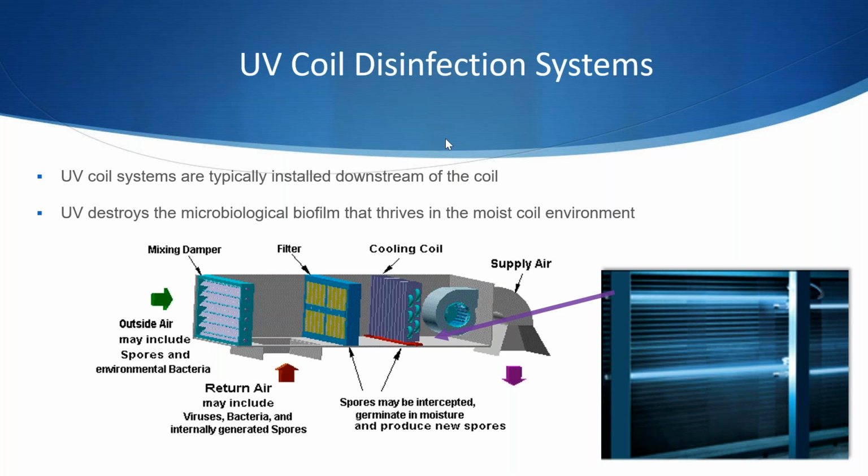So if their goal is only cleaning coils, then the best location is on the downstream side of the cooling coil, with sufficient space there to be able to space it far enough to have the irradiation cone from the lamp spread out and cover the fullest space of the coil possible. On the drain pan side, so you're able to irradiate the drain pan as well. Very best location. If they're talking about airstream disinfection and they have enough space there, that's a great place to locate it also, because then you can benefit from the coil cleaning while you're getting your airstream disinfection.